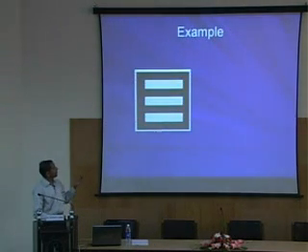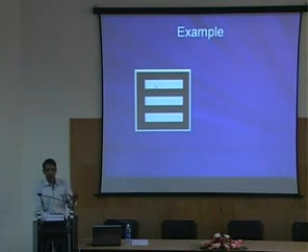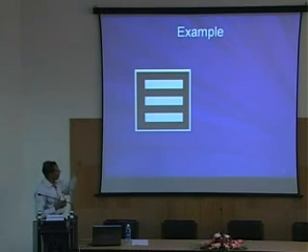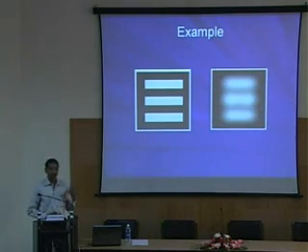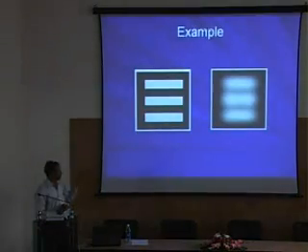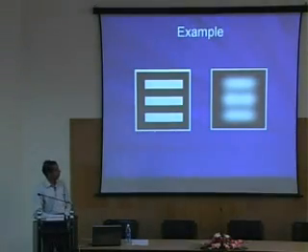Now, if I had to, let us say, define a feature as I have shown here on a silicon wafer, and if I am using conventional optical lithography, then obviously if the wavelength of the light that I am using is comparable to the feature size itself, then when I am trying to define this on my silicon wafer, this is what I will get. So this is a major problem, and that is why we are unable to push the silicon technology further, because of the limitation associated with photolithography.